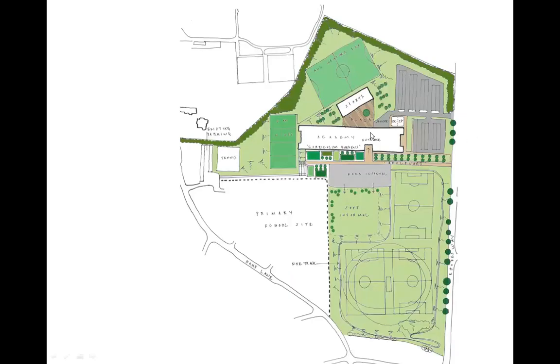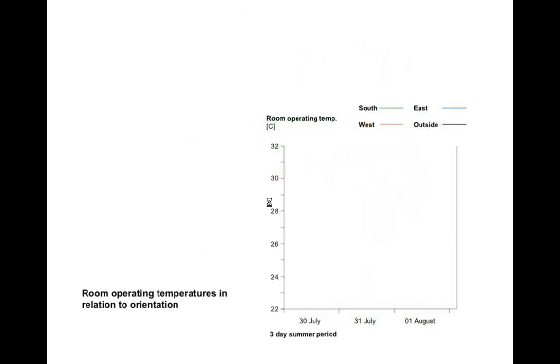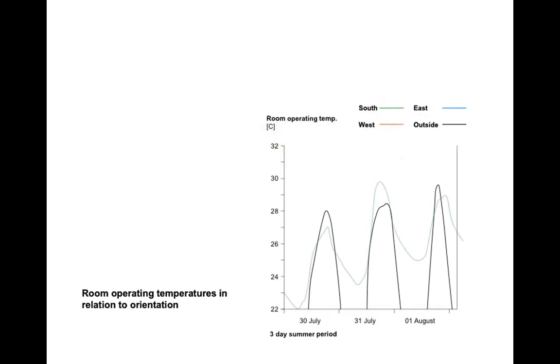by optimizing our orientation, our west facade is tiny. And in fact, that west facade didn't have any windows in it. So we're minimizing the problem facades, which makes it much easier to design. Now obviously, on some sites, you don't have any choice of orientation. Okay, let's just go on to the next one.